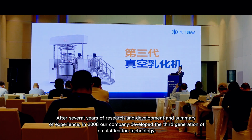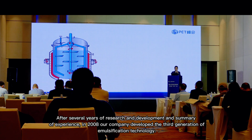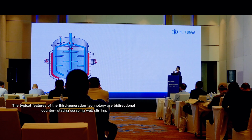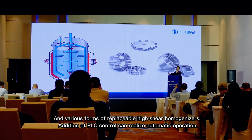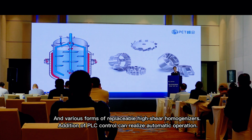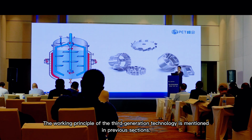After several years of research and development and summary of experience, in 2008 our company developed the third generation of emulsification technology. The typical features of the third generation technology are bidirectional, counter-rotating scraping wall stirring, and various forms of replaceable high shear homogenizers. Addition of PLC control can realize automatic operation. The working principle of the third generation technology is mentioned in previous sections.